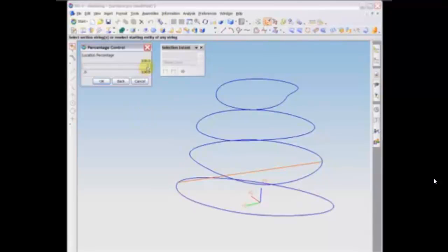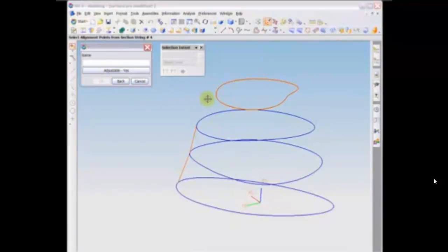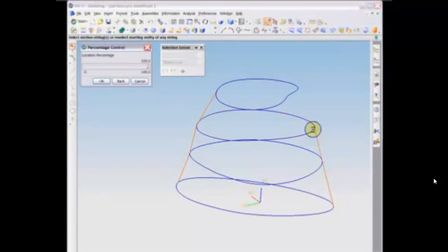You must then do the same for the remaining curves. You can create as many pathways around your profiles as you like. The more points you select, the more control you will have over the construction of the surface. When you are finished, simply choose OK.